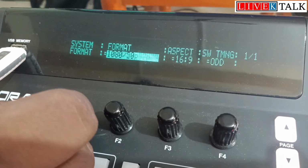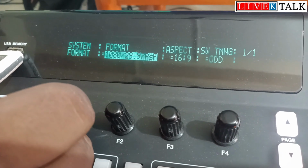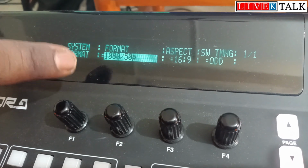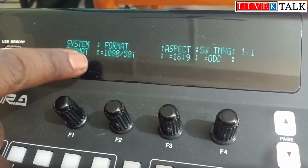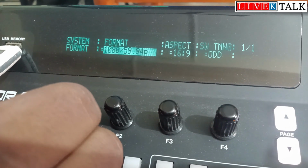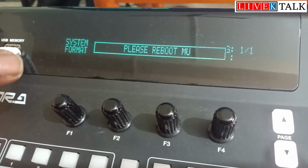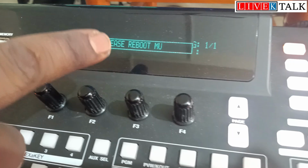Different types of formats are there. You can select it from here, and when selecting, the switcher will want a reboot. We have to reboot the switcher. Suppose the switcher right now is in 1080 50i format. I want to use it in, suppose, 1080 50p. So what do I have to do? I have to select, then the switcher says please reboot the main unit. It means I have to reboot it.